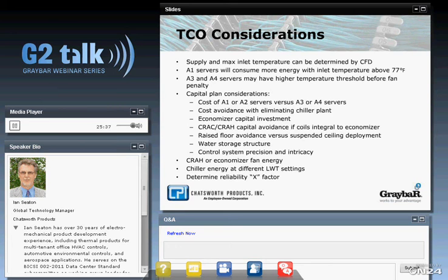Look at our economizer capital investment and also the operating cost for our economizer, and also look at the ASHRAE handbook best practices for datacom facilities energy efficiency that will give you a chart for your operating costs for chiller plants at different water temperatures, and that should go into this budget as well.